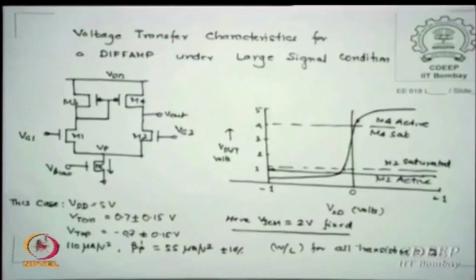So one of the specs of a difference amplifier, or for that matter an op amp, is the output swing, how much output maximum you can achieve from a given circuit which you design. The other of course is how much maximum to minimum input I can vary which will still give me gain, is that correct? So what does that mean? The device still remains in saturation for those inputs; beyond that they may not.